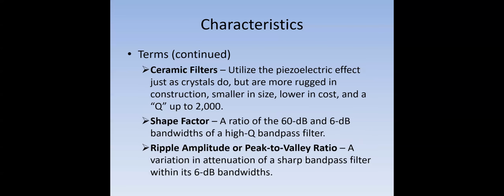All right, ceramic filters utilize the piezoelectric effect just like the crystal, but are more rugged in construction, smaller in size, lower in cost, and have a Q up to 2,000 instead of 50,000. So a Q up to 2,000 is actually pretty good. But these ceramic filters are a little less expensive.